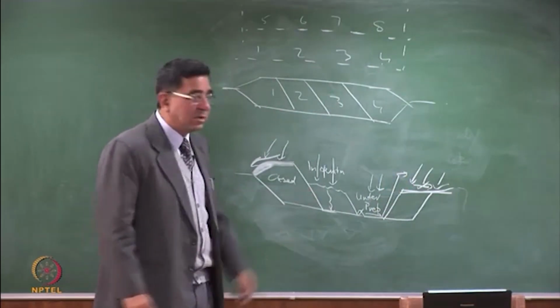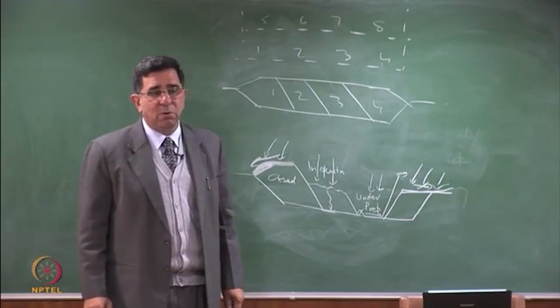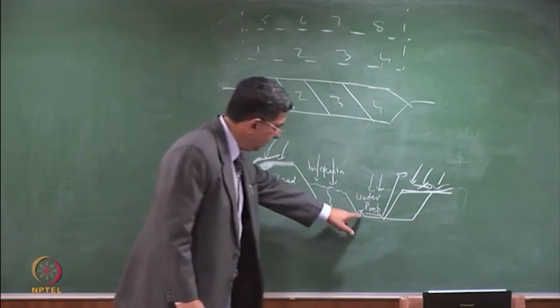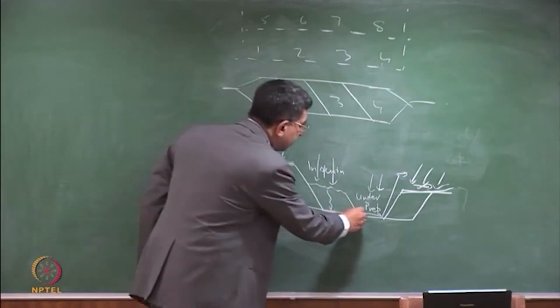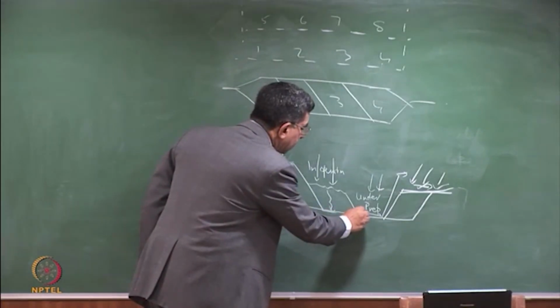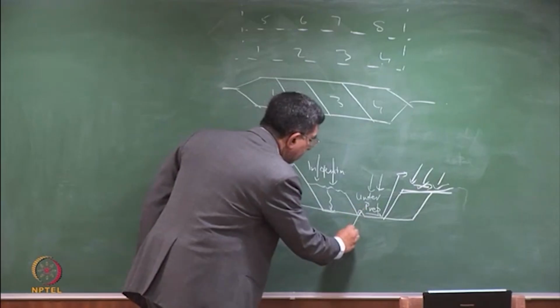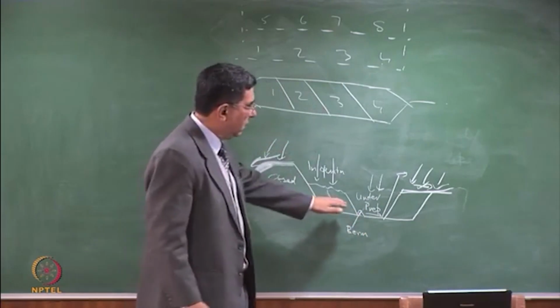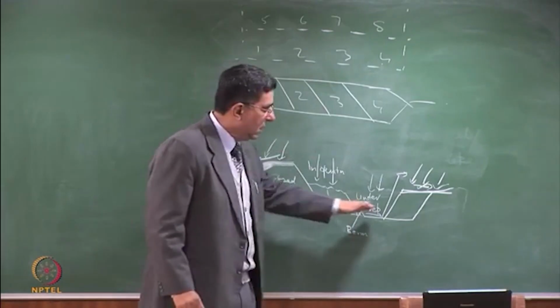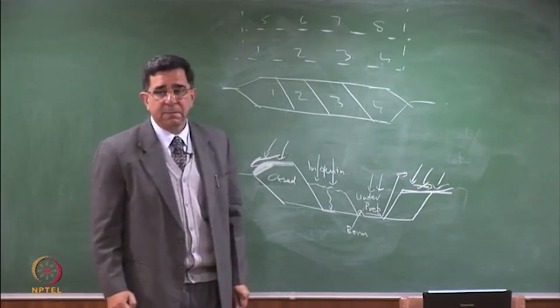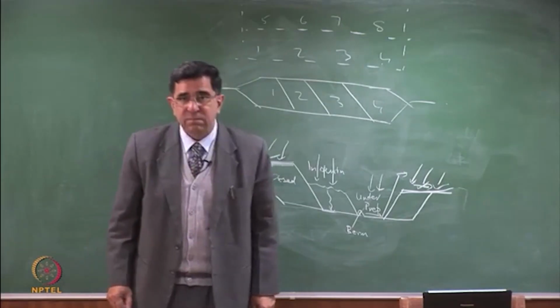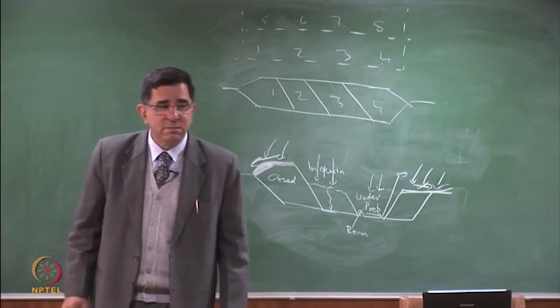The moment it becomes leachate, you are prevented by law to put it into the stormwater drain. And this berm is very important. It separates the leachate, keeps it inside this, and the surface runoff on the other side. Any confusion?